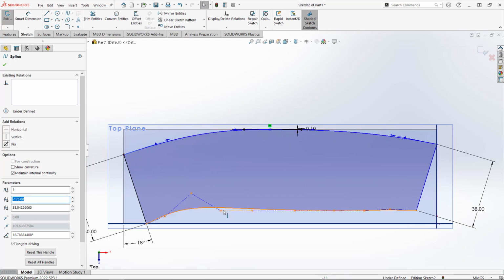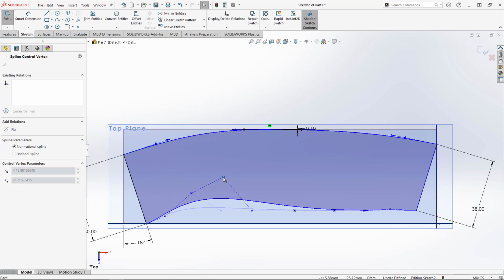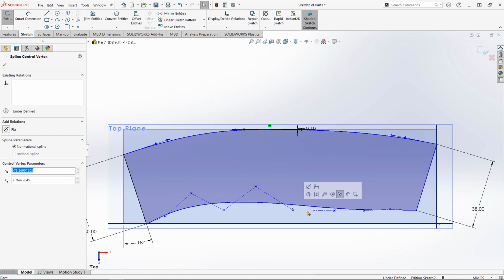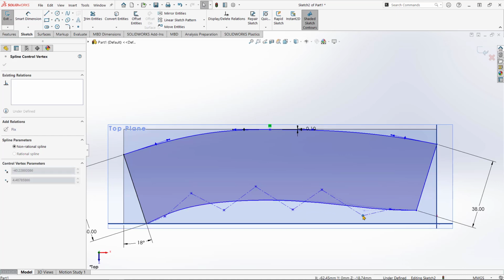Whereas the style spline is surrounded itself by this kind of cage work of points, and it's dragging those points that actually affects the shape of this spline. So in a moment we're going to see quite a dramatic change in this spline. By default, these style splines are set to be highly smoothed.